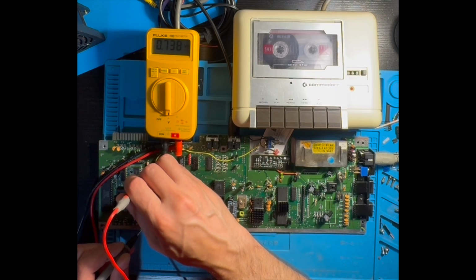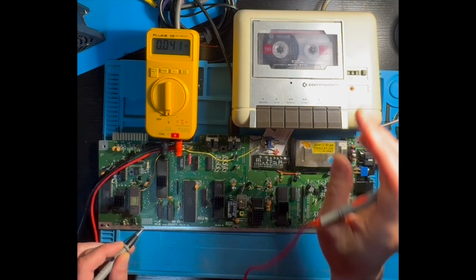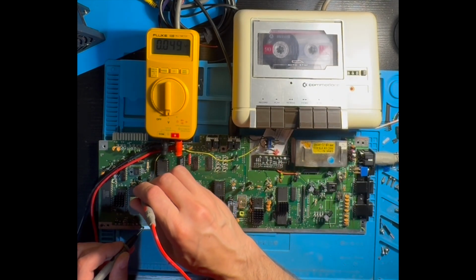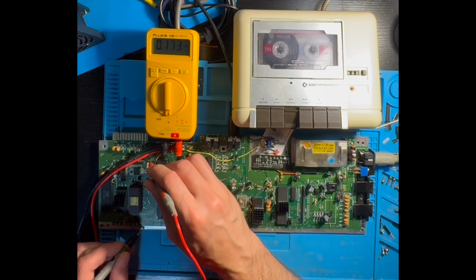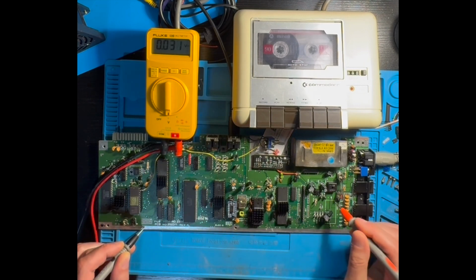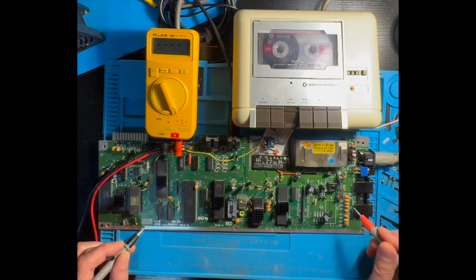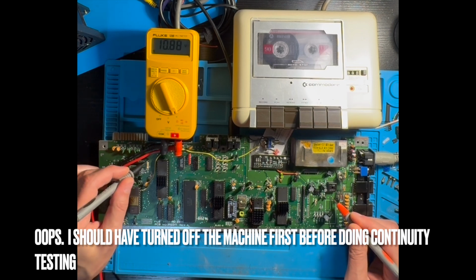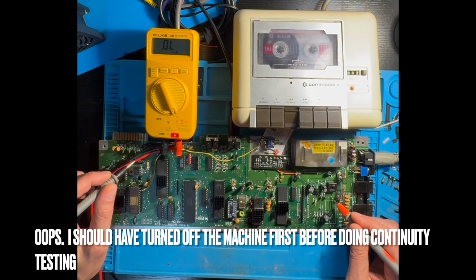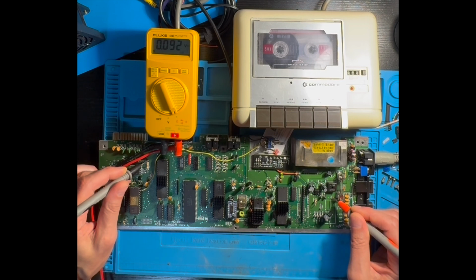And so I'm going to look through and just check different points to see where voltage is and where it isn't. And I can see that this side of the board, right around that voltage regulator, it's not doing what it's supposed to. On the capacitor side, it's good. So it looks like it's just not getting from one side of the board to the other. And the continuity test, it's not really registering correctly. So I think there is some kind of break, or something on the board isn't actually connected from one side.